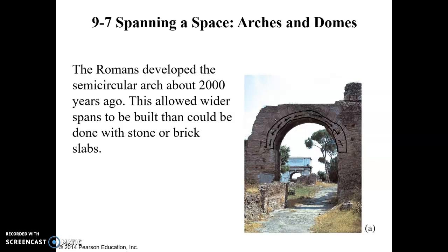So if you've got an arch that's supported in a wall, that's fine, that will help, because all these outward forces will be counteracted by the mass of all of these bricks to either side. And then the downward force is just accepted by the compressive stress of the rocks and whatever foundation it's sitting on. Okay, so an arch buried inside a wall, very strong, very good at carrying load.